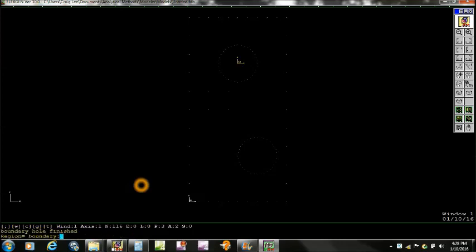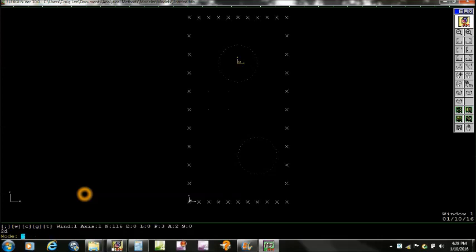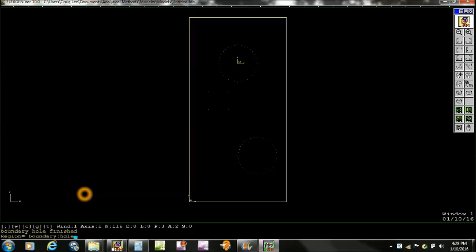Now what we want to do is define the region that's going to have the mesher come in and mesh the elements in. We do that by defining a boundary around it, and then we define holes within that boundary. So we're going to do a region boundary, and nodes 1 through 40 form that boundary, and that's the boundary right there of the plate.